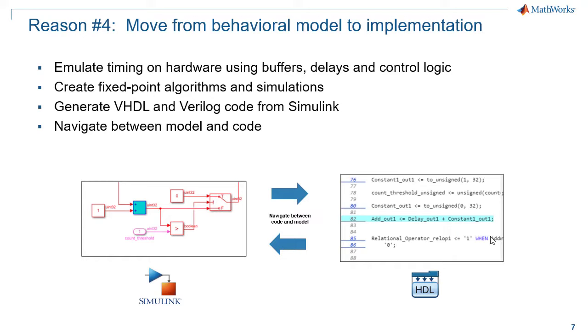Lastly, you can start to move from design to implementation to be hardware ready all in one platform. Use buffers, delays, and control logic to emulate hardware behavior in your simulation. Convert your designs to fixed point. And lastly, with a push of a button, generate HDL or C and C++ code for hardware-software co-design. You can also determine which block in a model corresponds to a given line of generated code and vice versa. This makes traceability a straightforward exercise.